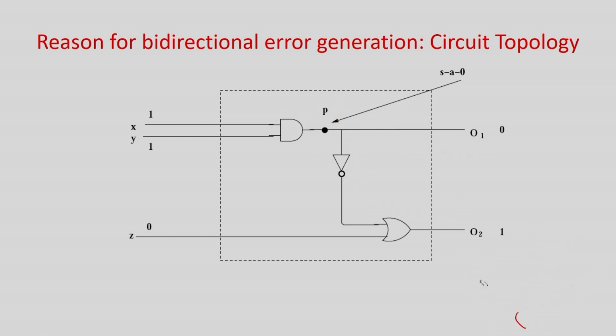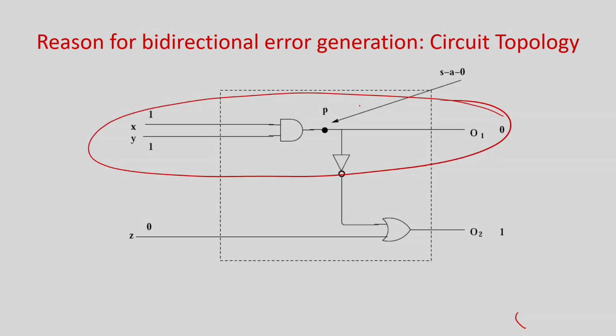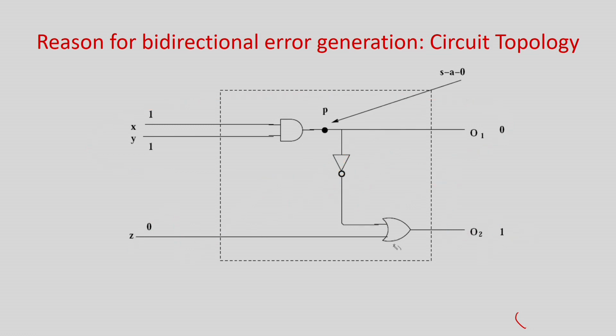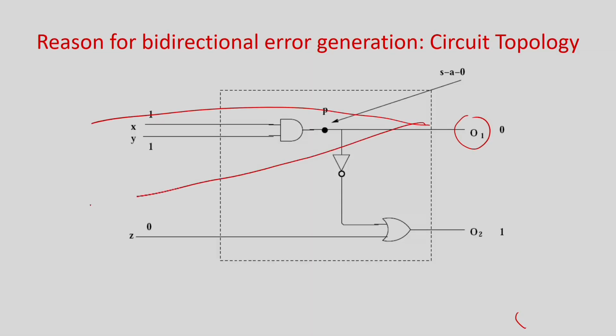If I can replicate, for example, this is one output, right? We can say that this part of the circuit is giving the output O1. So this one circuit is there, I eliminate the other part. So one circuit is just like this, and it delivers the output O1. Next, what I am trying to tell you is that I am not going to allow sharing of gates. For example, this output is dependent on this gate, and output O2 is dependent on this gate as well as this one.